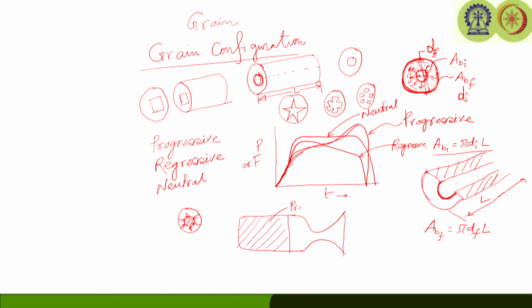So, this is the propellant grain. Now, burning is going to take place longitudinally. As time passes, the burning surface area will still remain constant over time.